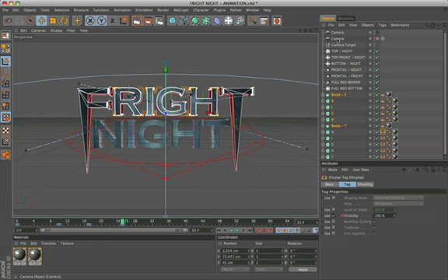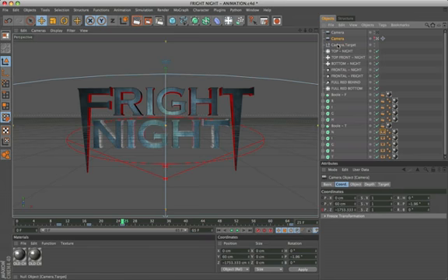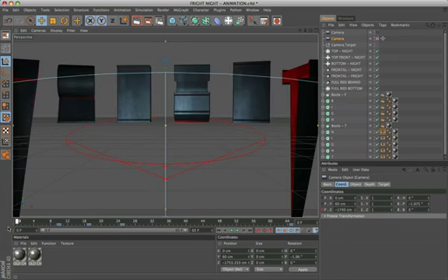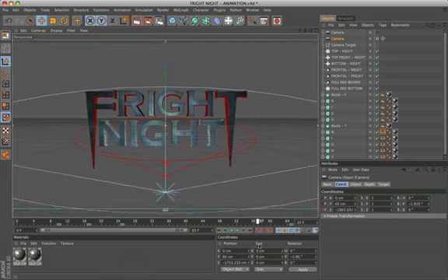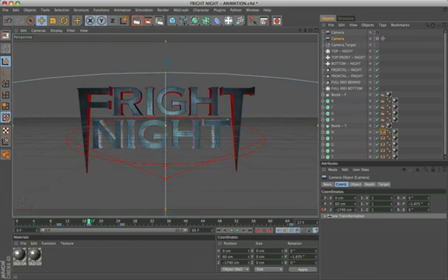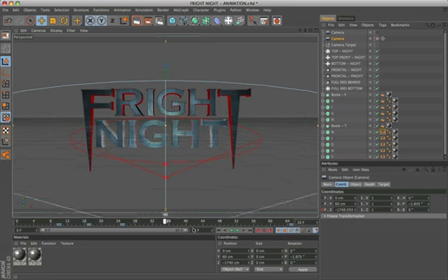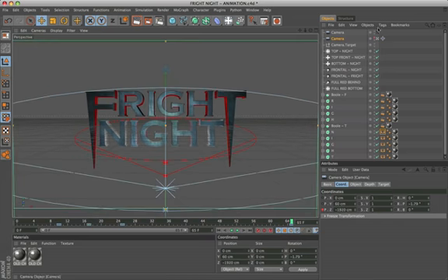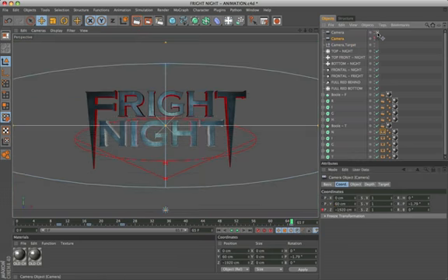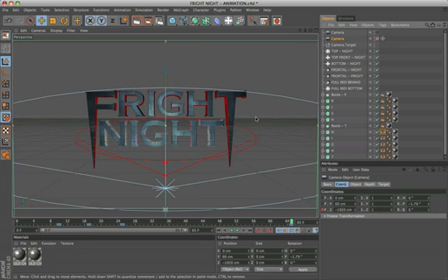Now I show you why I used the camera target. Given that, the camera has a small sequence of Z position, from frame 17 to frame 65, for the final position. Thanks to the anchor target, which is positioned at center scene. Inserting in the camera, on Y, the value 60, it automatically creates a rotation P, to -1.79 degrees. This slight tilt allows you to have the logo as the original video. Very simple.